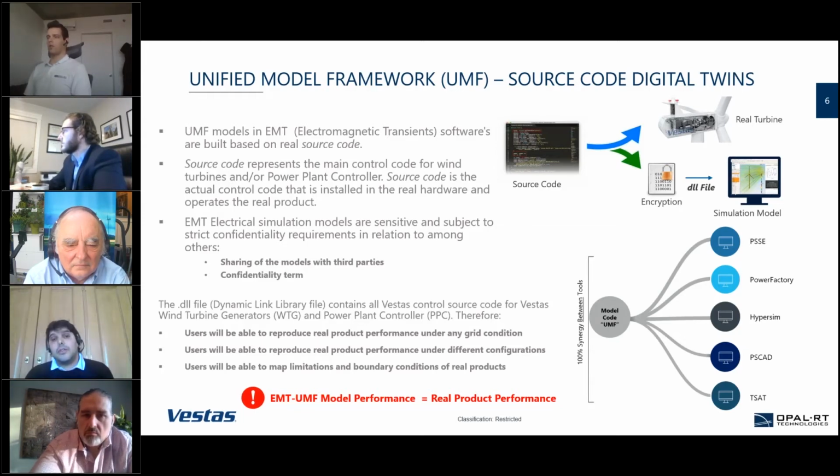In order to do this, and this will be the position I would say of most of the OEMs, we need to protect the intellectual property somehow in order to increase the accuracy and fidelity of the model, and that's why we compile this into encrypted DLLs or lib files when we ship out the models. It is important that these models are able to reproduce the real product performance under any circumstances.